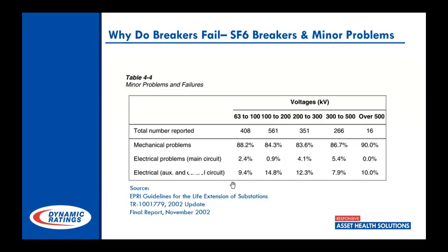So if you look at a typical scheme, you may have distribution breakers, and then you're going to have a bank breaker between those distribution breakers and the transformer. And generally, you're going to have some type of delay there. So a fault occurs on the line, distribution breaker is supposed to pick that up. The whole system's looking at it at that point, and you may have a 15 cycle delay set between that bank breaker and that distribution breaker. So it's counting. Well, that distribution breaker does not operate. Now we're 15 cycles out from seeing that bank breaker actually interrupt that fault.